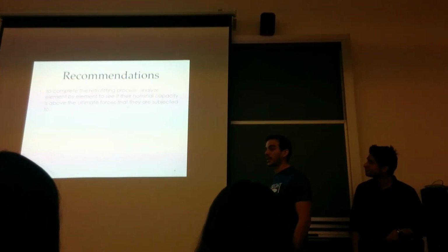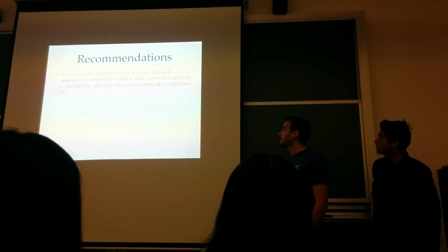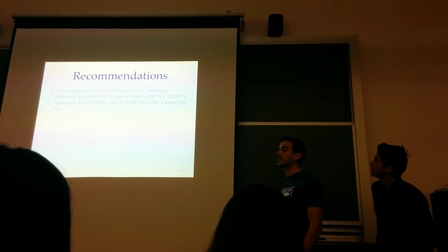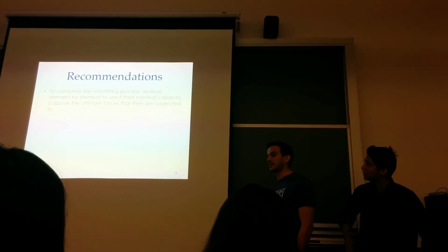As for our recommendation, after what we just did, we recommend to complete the retrofitting process, analyzing element by element to see if their nominal capacity is above the ultimate forces that the structure is subjected to.